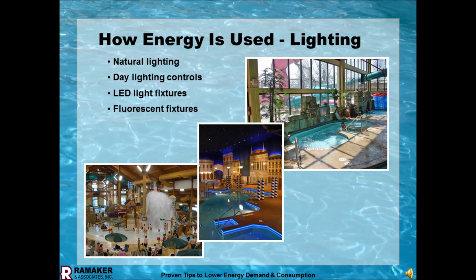Again, you put the VFDs on it. You can cycle the RPMs back and cycle the pump rate from 15 minutes back to 30 minutes. You just reduced your energy consumption significantly, but you need to be monitoring this. This isn't something that you're going to do and forget about, meaning that you don't want Tuesday morning to turn into Friday evening and Saturday and maintenance forgot about it.